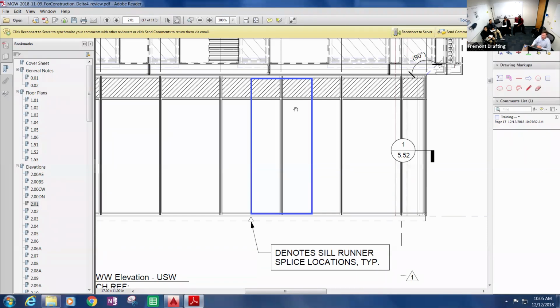Okay, so as I'm considering when trying to determine the deflection of this mullion and wind load, the tributary area that's contributing to that deflection is going to be the wind load on this half of this piece of glass and this half of this piece of glass, for the full height of the mullion.